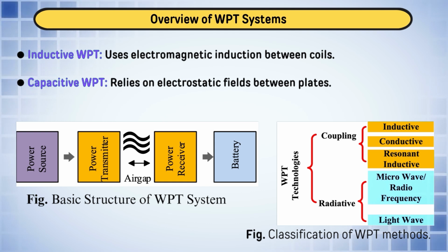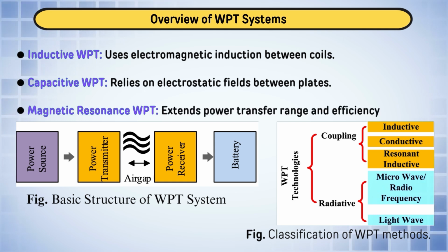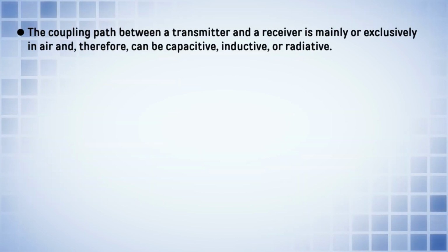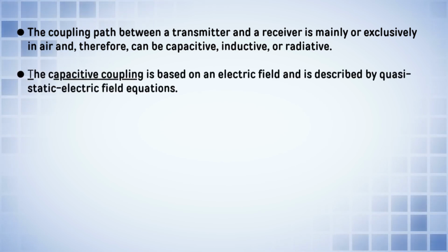Similarly, for single phase application, suppose we have utilized a single phase front end converter for the AC to DC conversion unit. The single phase source is available in India as a 230 volt and 50 hertz supply. This 230 will be converted into 325 or 310 volt. This 310 volt can be stepped down using a buck converter, right, because the battery requirement is suppose 48 to 72 volt.